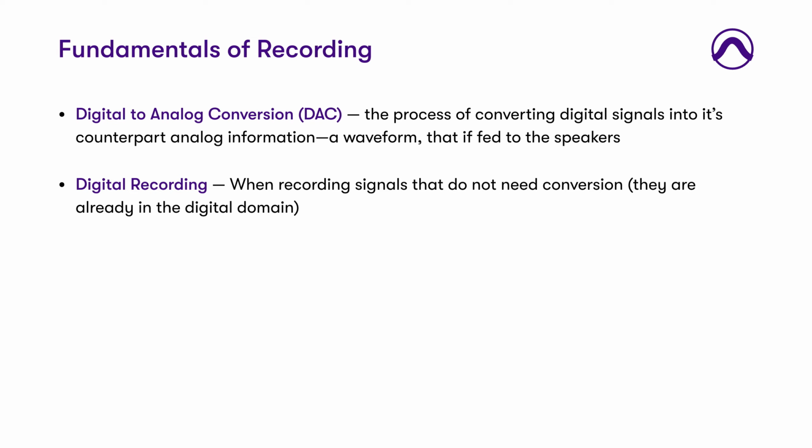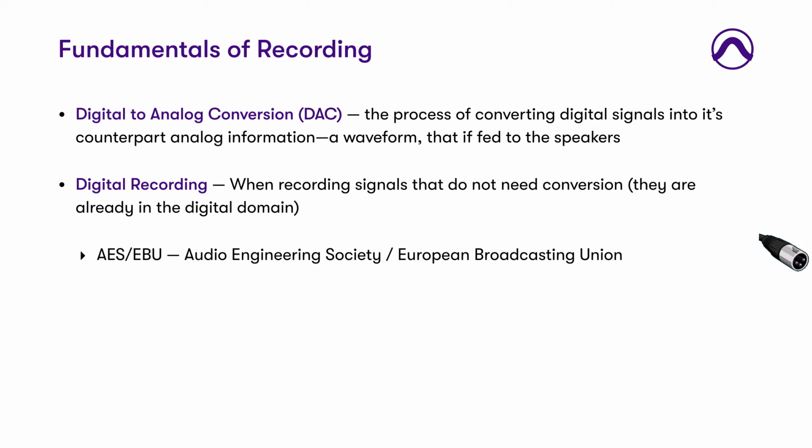Because both my source and my destination are already digital, there are two connection types that I can use to transfer audio digitally into my digital audio workstation from an external source. The first is what we use mostly in the professional or studio environment, called AES-EBU, or the Audio Engineering Society European Broadcasting Union format.